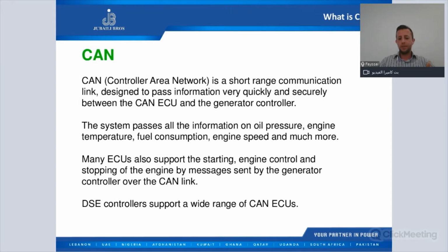And it helps us to communicate with the engine ECU. ECU stands for Engine Control Unit, or in some other cases, you'll see it written as ECM, which stands for Engine Control Module. So the system passes all the information on engine parameters like oil pressure, temperature, fuel consumption, engine speed, and much more.